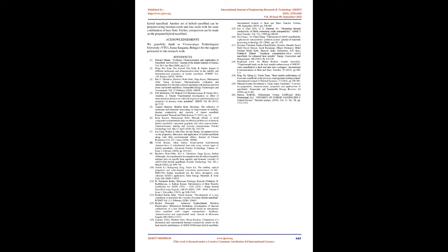8. Overall heat transfer coefficient increases with increase in nanofluid flow rate. However, CNT/water nanofluid results in enhanced heat transfer when compared to water at two different heat sections. 18. The suspended copper/water nanofluid can remarkably improve heat transfer behavior of the base fluid, and heat transfer coefficient increases with increase in volume fraction of nanoparticles.